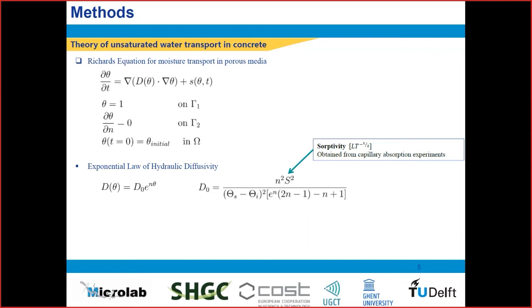So mathematicians before us actually solved that problem for us, and through a number of assumptions, and provided that the temperature is kept at 20 Celsius degrees, we can arrive at the so-called Richards equation, which is widely used for the modeling of moisture transport in porous media. With this equation, you arrive at a sort of diffusive process of moisture inside the porous medium. And it's quite simpler, as I hinted before. So assuming that the temperature is always 20 Celsius degrees, we are fine and we can solve the problem much more easily than if we had a coupled system of two partial differential equations.